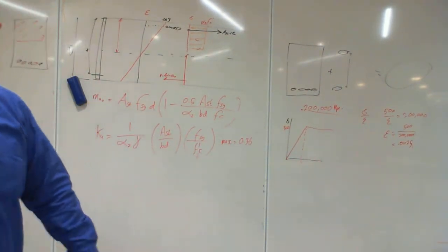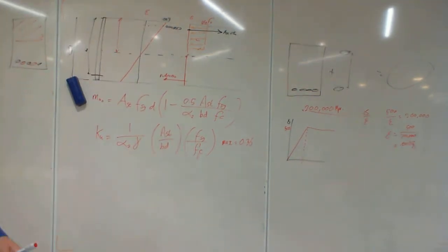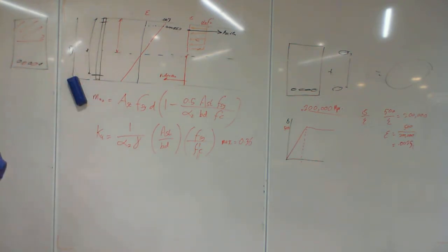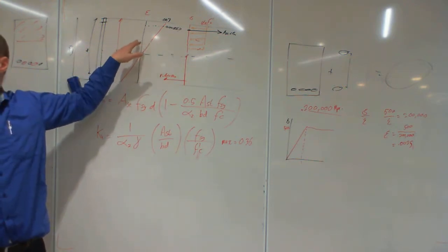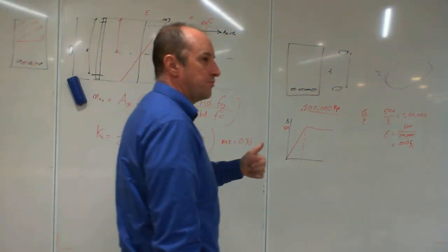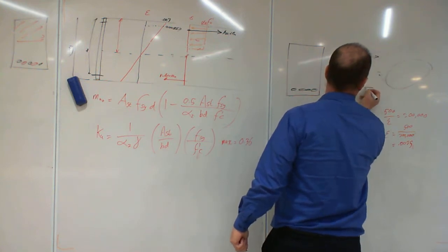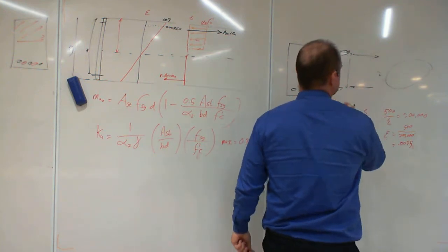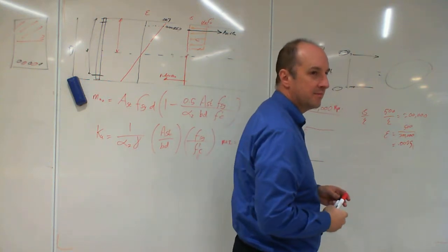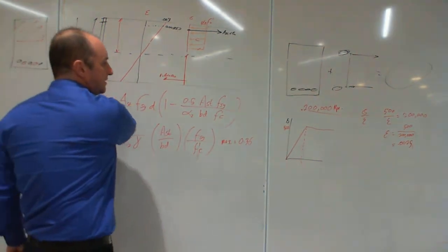Okay. Now there's a formula in that textbook about the depth to that steel versus the depth to that steel minus this minus that. But basically, all it's doing is using triangles, looking at the geometry and saying, has that yielded or not? Okay. So that's the first complication. If it hasn't yielded, then this lever arm here, that's going to be less force than that one, so it's out of balance. So we have to adjust the beam for that. Okay? All right, any questions so far? Okay.